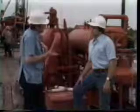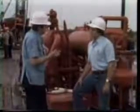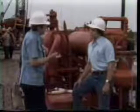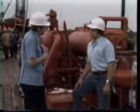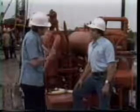You flow at a single rate until you get stabilized pressures, which has some definition in Louisiana, like 1% pressure change or some equivalent like that in a certain period of time. Is that right? It's 1% in 15 minutes. In 15 minutes. Right. Okay, good. Now, it should be recognized that such rules of thumb may be in error.